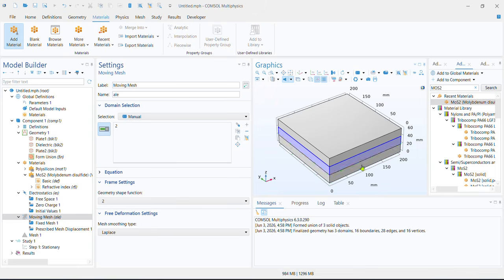and you make sure only the center mesh is created as moving mesh. Now what moving mesh does: we're trying to sweep the top block up and down to check the capacitance, varying the D gap, but when you do that, the center block will get deformed. So the mesh itself is getting deformed and you get some error. Moving mesh basically tells the solver that you're expecting the center mesh to deform, and that's okay. Just remesh it every time you compute. That is why you have to mesh the dielectric, because you're moving plate 2 up and down.